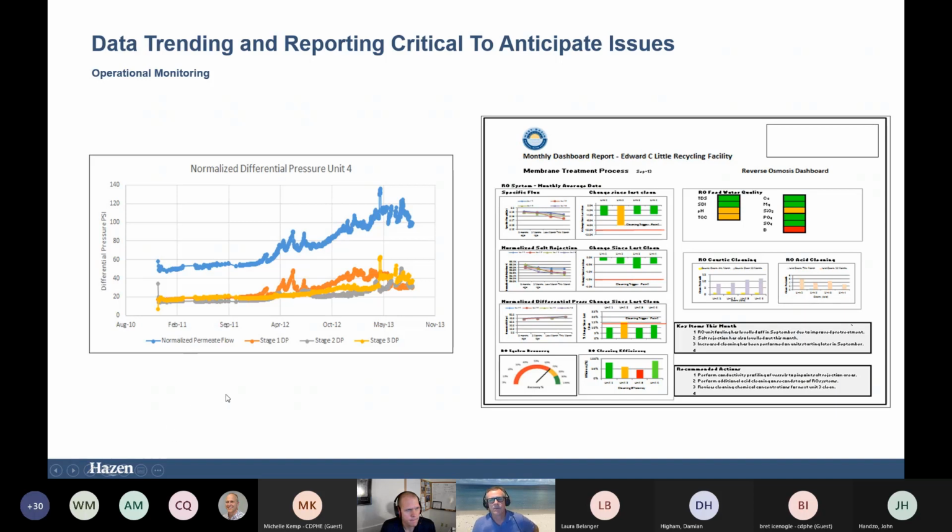The last thing that I will say, and I should have put a slide on this and I didn't, is that as you think about this, you're reliant in operations as much on the analyzers and the ability of those analyzers to detect a problem with the barrier as you are with the barriers themselves. If you think about it, a true failure of a critical control point system is not if the barrier has some kind of breakthrough, because we've got monitoring to detect that. We've got controls and operational responses to respond to it. The true failure is if our analyzers fail and we don't detect that. And so a lot of focus on calibration, validation, and maintenance of analyzers is very important.